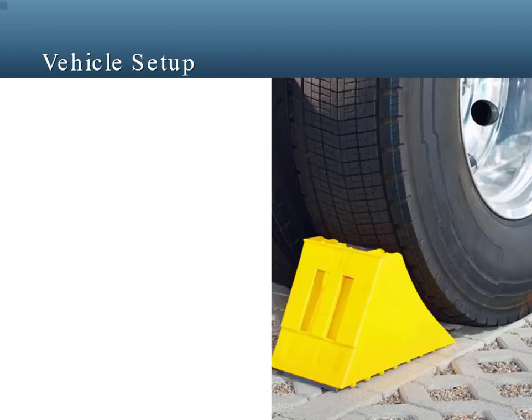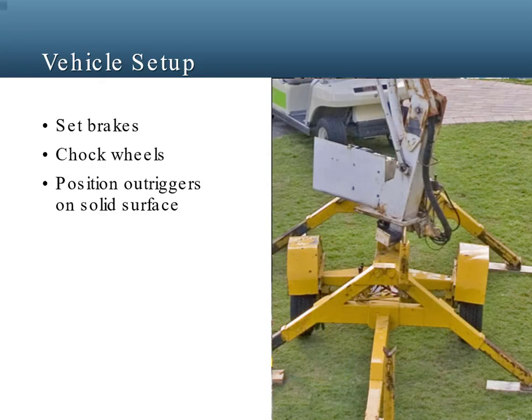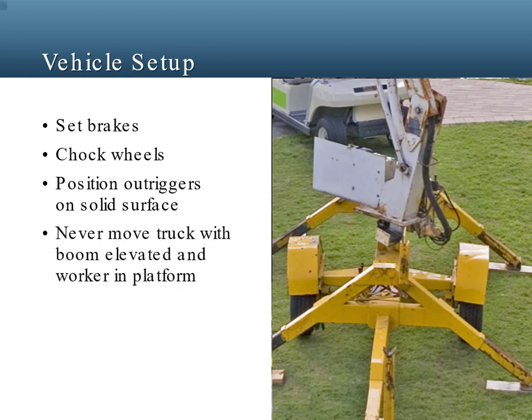Once inspections are conducted, you need to make sure the vehicle is properly set up. Set the brakes so that the vehicle will not move while the lift is elevated. Place wheel chocks under the tires. Position the outriggers or stabilizers on a solid surface. Never move the truck when the boom is elevated with a worker in the platform.